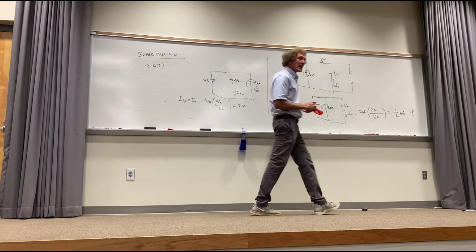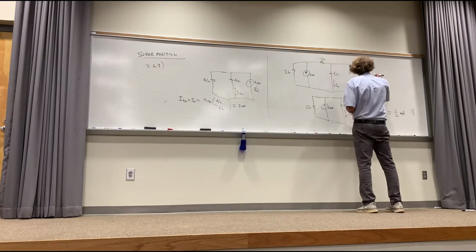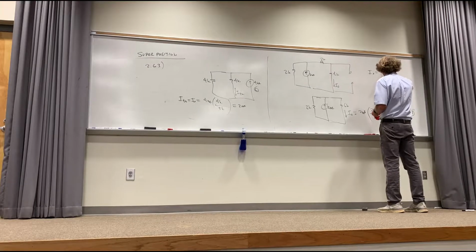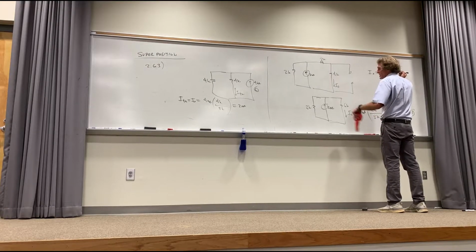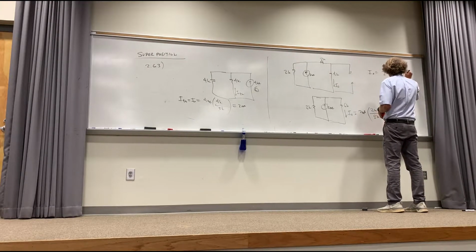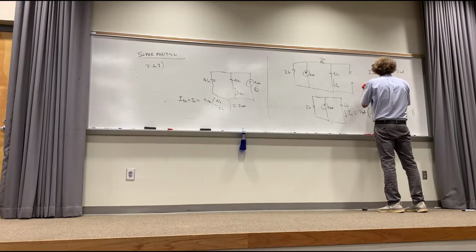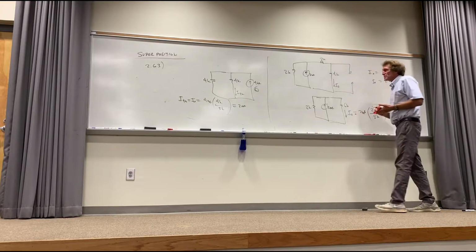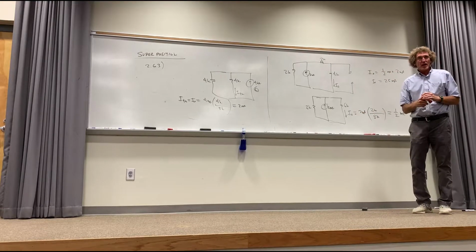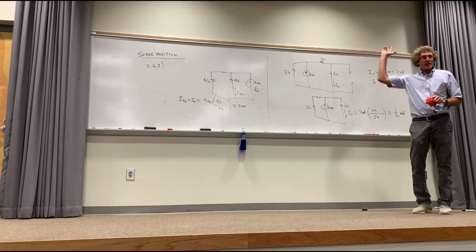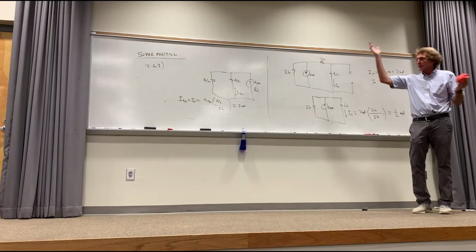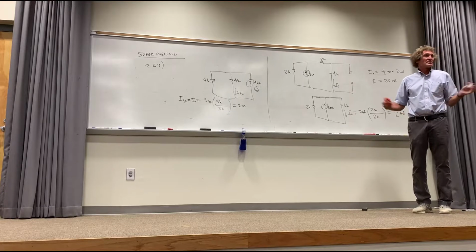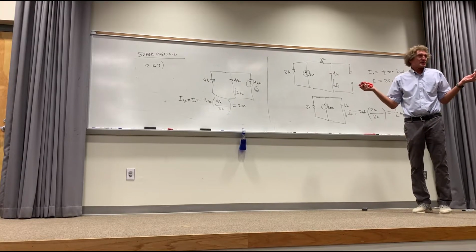Which means the net output, now my total, the actual value for I out, or I4K, would be 1/2 milliamp plus 2 milliamps, or it's simply going to be 2.5 milliamps would be the answer using superposition. Do you appreciate what I'm doing here? I'm going to do one with a voltage. How many see this right here? This is superposition. The nice thing about it is most of the time, you don't need anything more than series parallel combinations that you have to take care of.